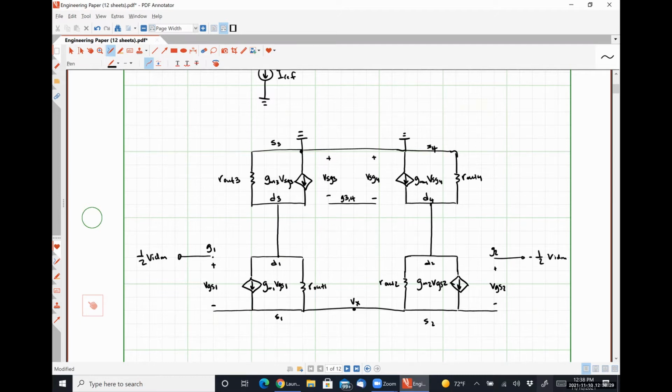And before we do anything else, I want us to take a look at this guy, okay? So I'm going to draw this bit here in red, fully understanding that I'm about to erase what I'm drawing here. So, all right. When we loaded our differential pair with PMOS current sources, this is what our small signal model would have looked like, okay? Everything is perfectly in balance. The left-hand side exactly matches the right-hand side. Everything is purely symmetrical.